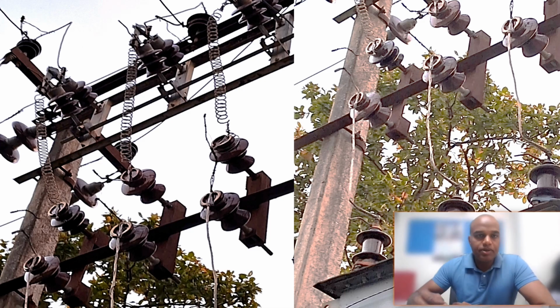If we zoom out the previous picture, now we can clearly see that the incoming 11 kV wires are connected through this insulator, and these wires are placed in this spiral shape just to provide more strength, and this wire comes down to here, and then the connection between these two insulators is made through a thin type of wire. So this wire gets heated up and melts down in case of heavy current, which is due to any kind of fault occurring.